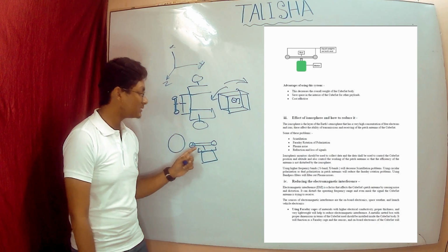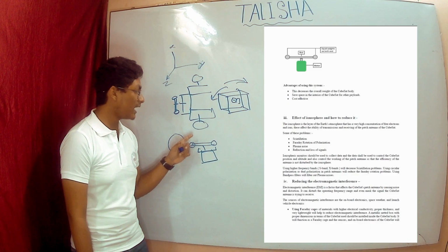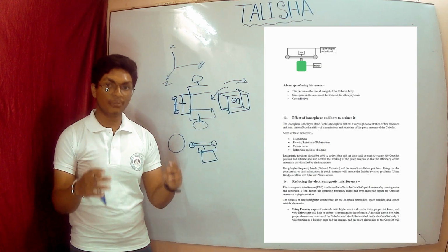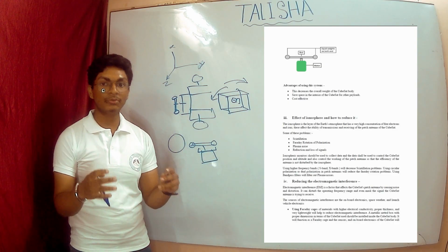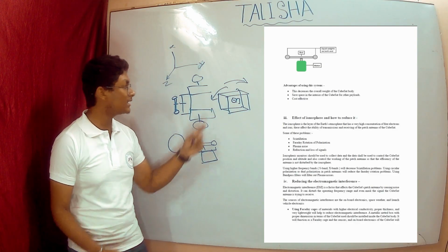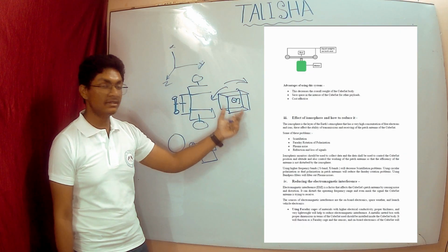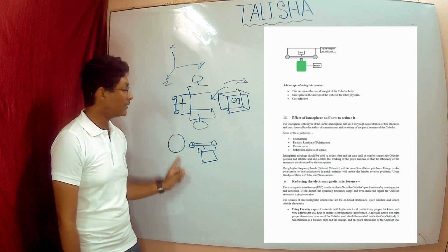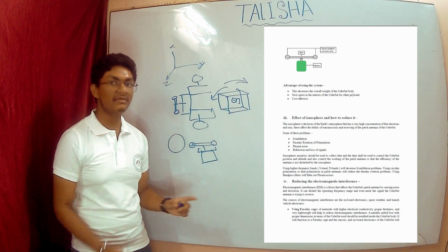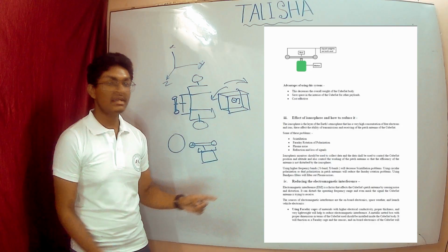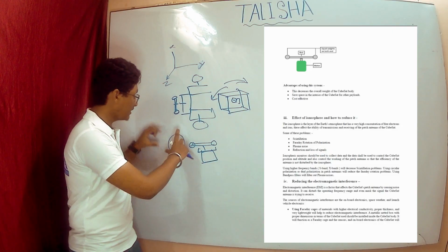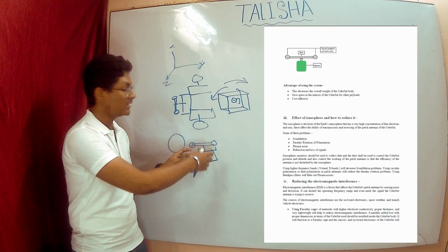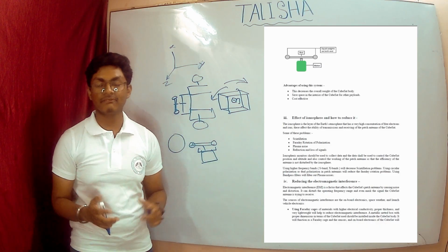Because this RPM or angular velocity will be more, it will generate the same or more angular momentum, which will be conserved by the Cubesat, and it will rotate in the opposite side, basically giving the same results as this. But the advantage is we will have more space in the Cubesat body. Materials will be saved, like we are taking a whole wheel and here we are just taking some pieces of it. Materials are saved and it is very cost effective.